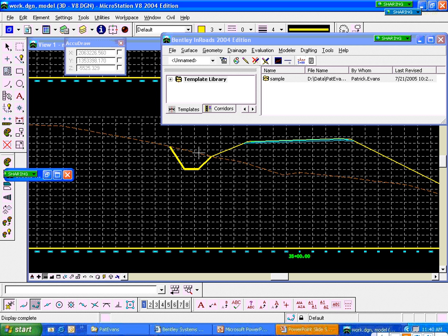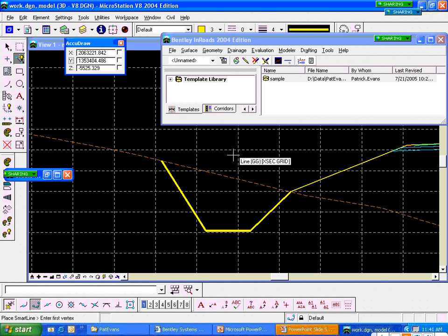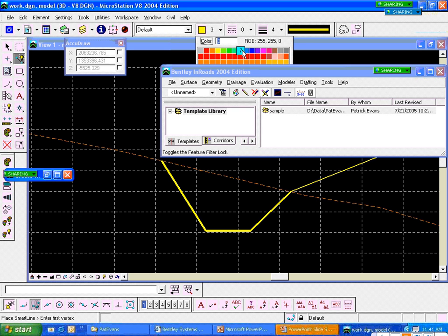And when you think about this, we actually have two targets. The targets are the same. It's the existing ground, the line that runs through here. We're going to tie into it one time, and then I'm going to go down and put my ditch in. I'm going to tie into it again. Well, you may be asking, how can we make this happen? Now, this is something we've been able to do in the past, and we can continue to do it. And let me explain a little bit of the logic to you as to how we're going to do this. We're going to tell, with our end conditions, to seek this point right here on whatever slope we choose to use, and then we're going to bounce up a little bit. We're going to go back up, and then let's change over here to a different color.